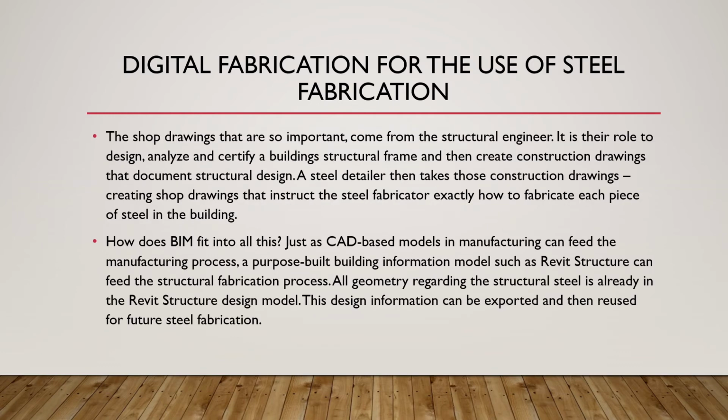The shop drawings that are so important come from the structural engineer. It is their role to design, analyze, and certify a building structural frame, and then create construction drawings that document the structural design. A steel detailer then takes those construction drawings and creates shop drawings that instruct the steel fabricator exactly how to fabricate each piece of steel in the building.